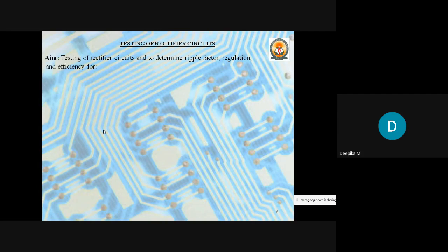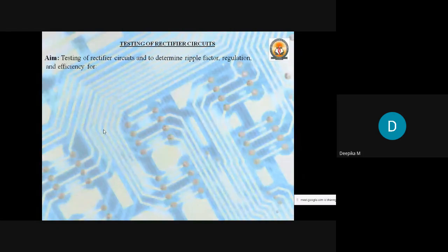Usually we build the rectifier circuit by using semiconductor devices, like power electronic devices such as GTO, FETs, MOSFETs. We all know that a diode is nothing but a semiconductor device, and it conducts current in only one direction. So here we are going to construct the rectifier circuit by using the diode. And coming to the application of the diode, mainly diodes are used for the switching action, that is for switching on and off the circuit.